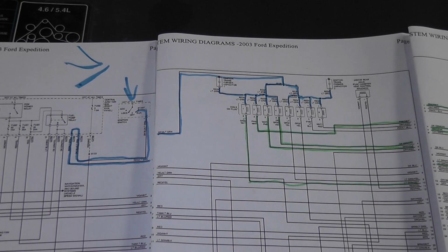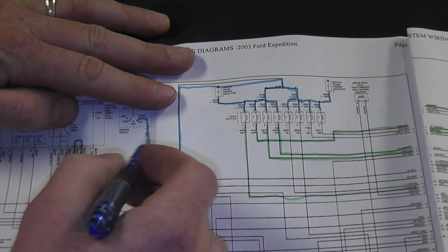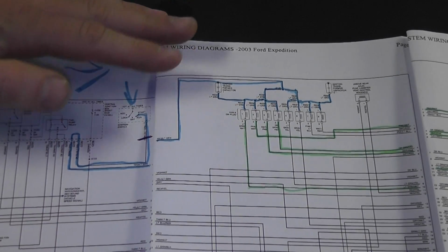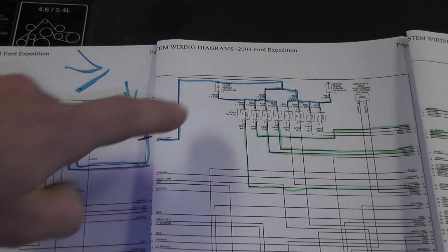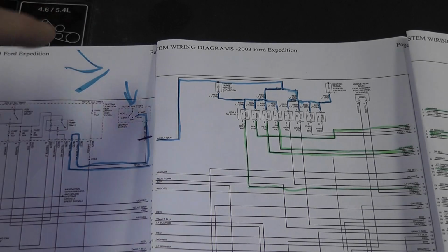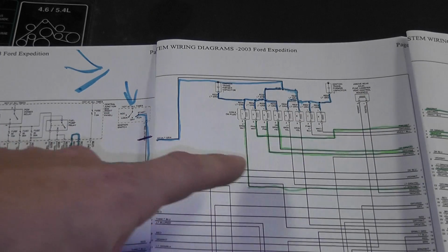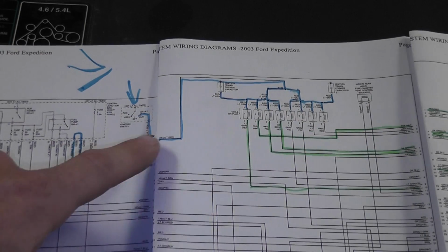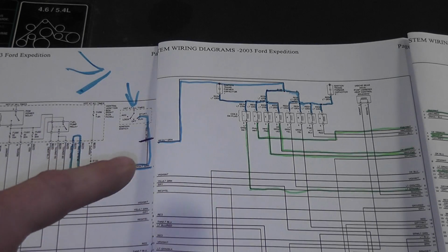Okay, so our first connection, we are connected to the wire that comes out of the ignition switch, where in this picture our amp clamp is right here. So we're going to read all of the coil current firing ramps from that feed. The only problem with this right now is that each coil is going to obviously fire individually, and so we're not going to know which cylinder is which by this first channel alone.